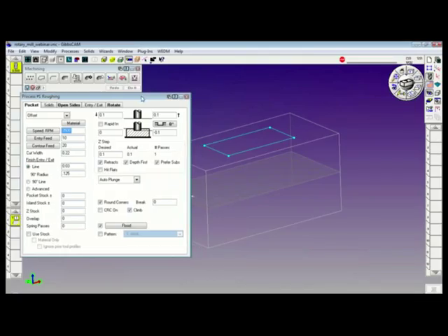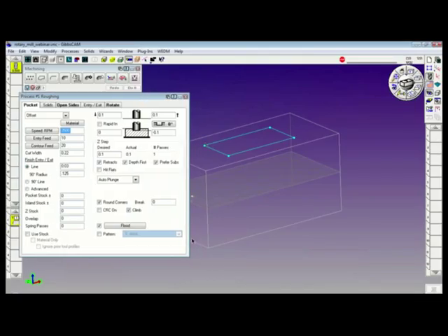Now, to set my depth values correctly, I like to interrogate the features that are on screen. For example, I want to determine the top of the cut right here. So to interrogate it, I highlight the dialog, hold the Alt key. It turns the cursor into a square interrogator.